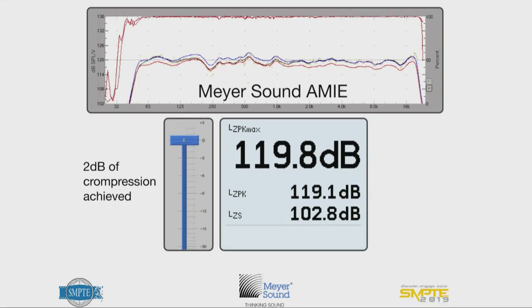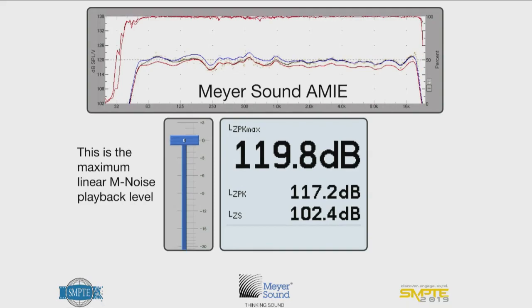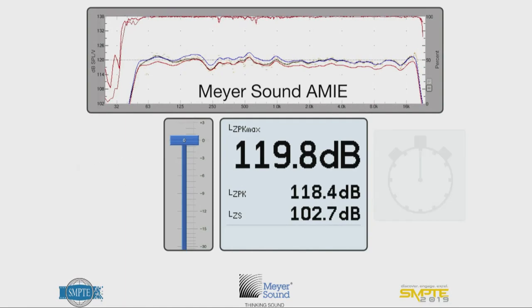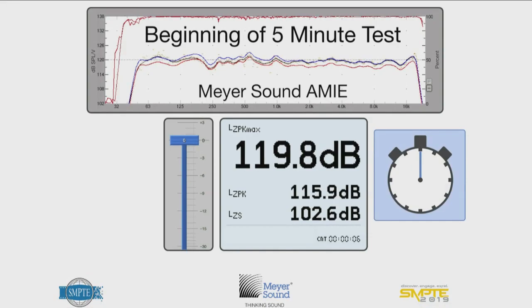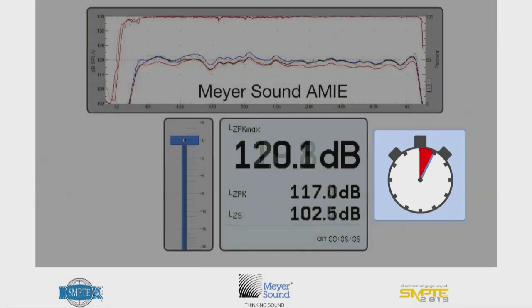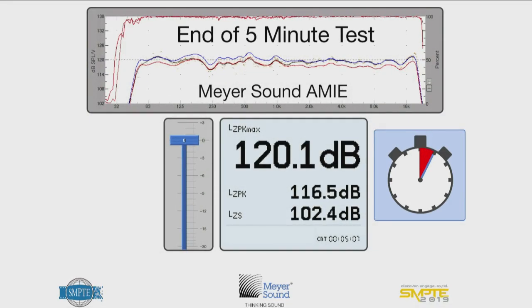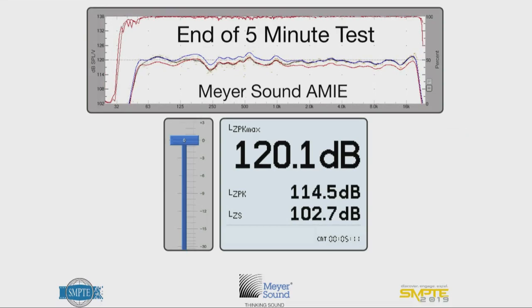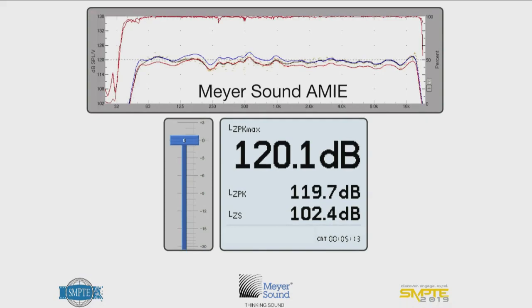And once it has, then we're going to let that play for a while. We don't want the speaker to get to the maximum and then die and never work again. You want it to actually be able to keep functioning. So we play it for some amount of time that you're concerned about, and then you record, okay, this is the SPL that it was at the onset of nonlinearity.